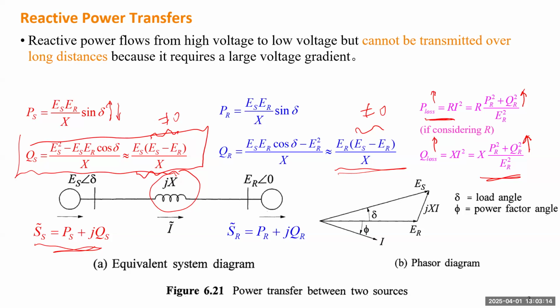But if that turned out to be ES much higher than ER, that's not reliable, because when you change all the voltages into per unit values, they can be different, but they will stay very close around one. For instance, for transmission systems, usually engineers expect a positive or negative 5% variation of voltage for high voltage lines. For even higher, like actual high voltage transmission lines, they expect the variation to be very small. Okay, not as small as frequency deviation, but it's still very small.